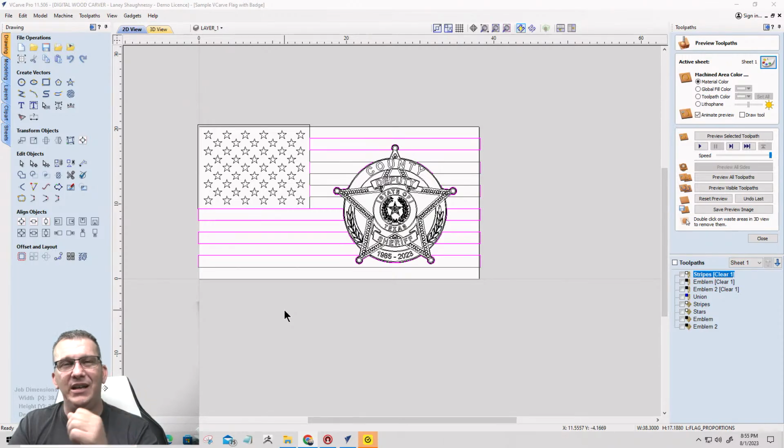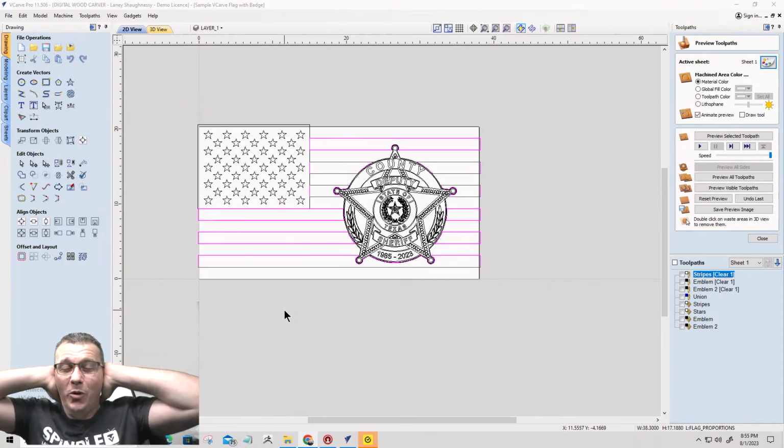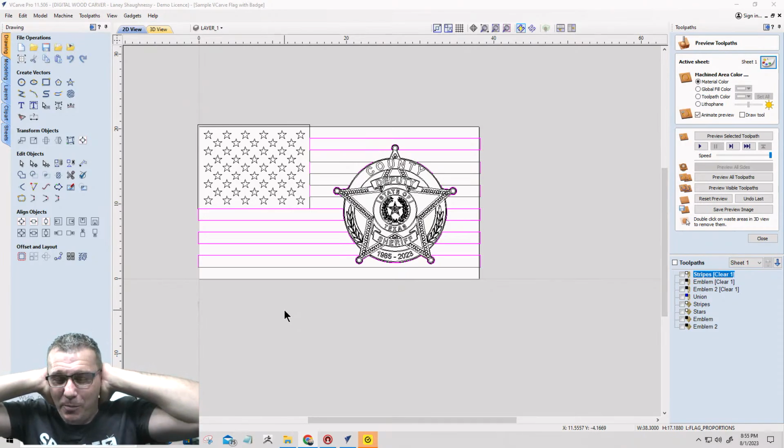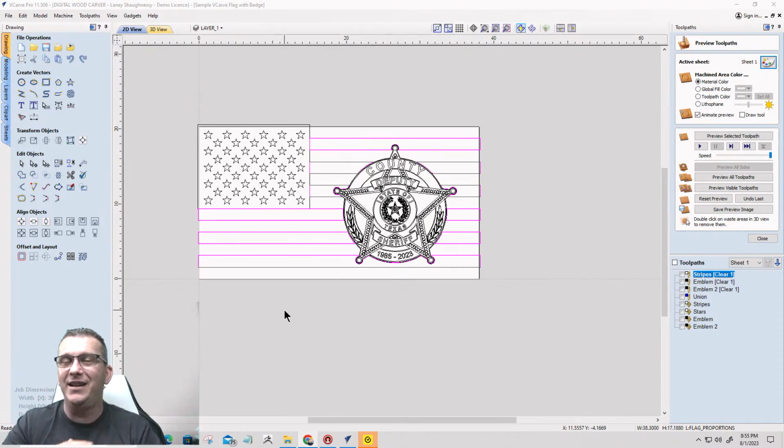That bit is just cutting through. The machine's not struggling. There's no torque on the router or the bit itself. You're not breaking bits every time you try to carve something. You're not going deaf because it's loud and pitchy, because again, that's too slow feed with the bit spinning too fast. If you're loud and pitchy, speed up the feed rate, turn down the RPMs. So give me a thumbs up if that explanation helped you, or gave you some food for thought for your next carve.